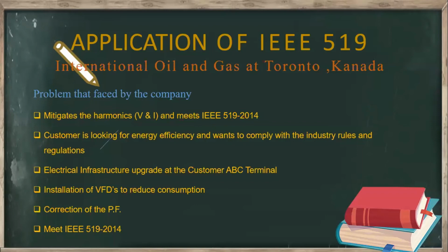The customer is looking for energy efficiency and wants to comply with industry rules and regulations. Third, electrical infrastructure at the customer's ABC terminal: installation of VFDs to reduce consumption, and correction of the power factor to meet the IEEE 519 standards.